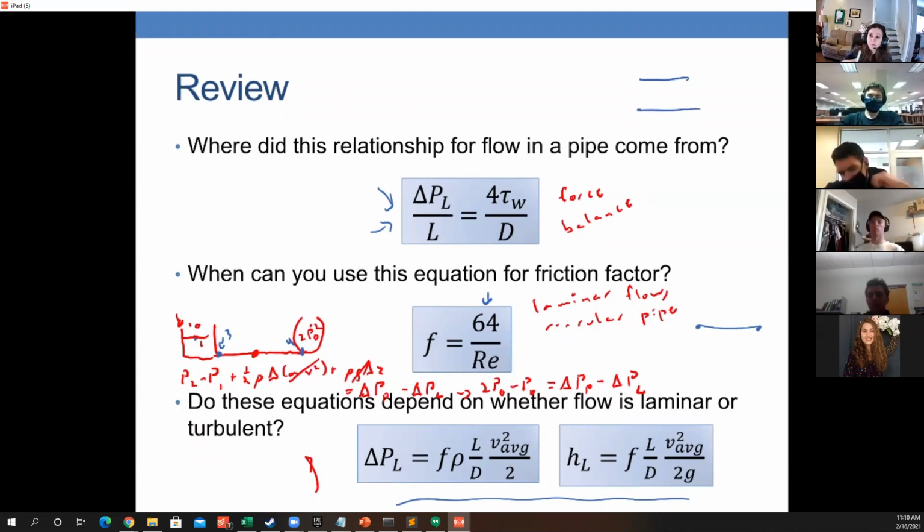What we would call the control volume here is that we're just cutting out a volume out of space. And that volume would be some section of the pipe, like this. The walls of it go all around the side, but then on either side you have this vertical surface that's just like a slice through, and the pressure pushes on that. Technically the pressure also pushes all around here, but it doesn't matter for what we care about.